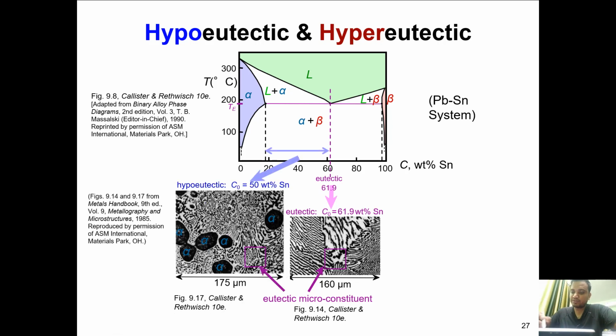Okay, so this is the microstructure you can see for this region, because in this region we have alpha plus beta. But this is also the point where we have the eutectic, right? So there will be some percentage of eutectic, and alpha plus beta at this point is the complete eutectic. As we go towards this, there will be some alpha phases also along with the eutectic, and if you go towards this, then there will be extra beta phases.